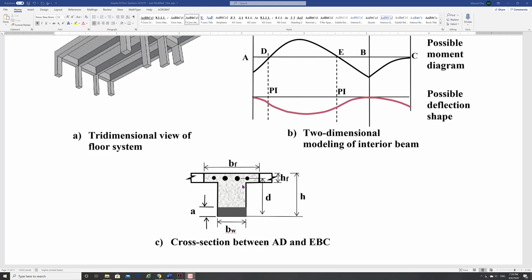A lot of designers try to concentrate this in the middle because of other construction issues, like if you have to make a hole in your slab, you don't have to perforate through your main bars. Some people may put just half of the total load and the rest may be spread through the edges of the flange. So there are different options depending on what you want to achieve in your design.